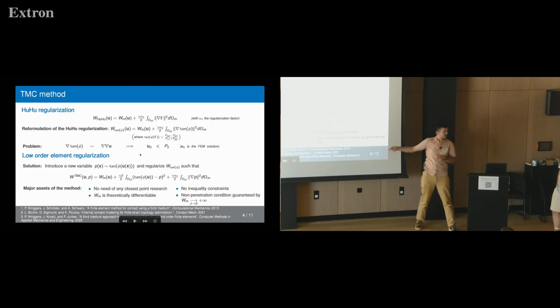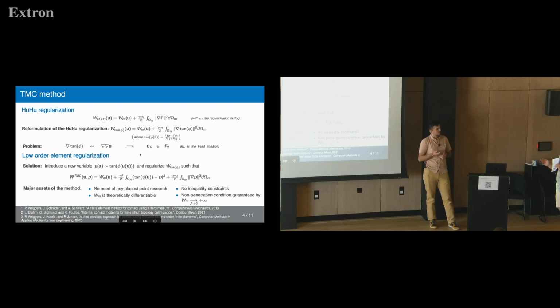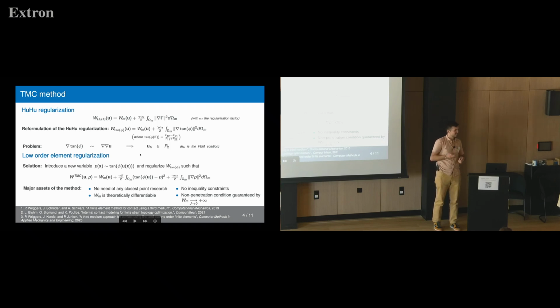So this one. Yeah. What I've seen with this is that the number of iterations you need is crazy. You need thousands of iterations in your Newton scheme, and you need a partial loading scheme. It might be better when you do time-dependent elastodynamics, but I've really struggled to get this to converge to what they have in their papers, even if the method looks super promising and would solve a lot of things. I would also be interested to see the iteration counts in 2D, because I've also seen that they're quite high for SNES, especially with hyperelastic material, it really struggles. So I would be interested to see the numerics from your side. I spent a weekend trying to do this and failed, kind of.